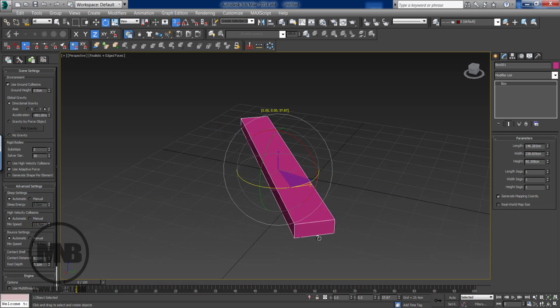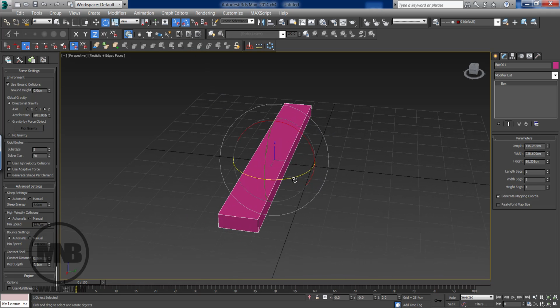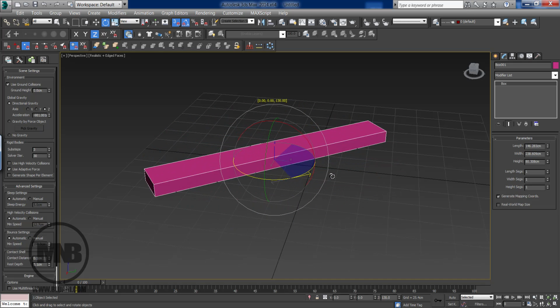If I want to snap, let's say 45 degrees, it's really hard to snap to exactly 45. It's a bit hectic because I have a decimal number. What I have to do, basically, is turn on my angular snap, and now I can just rotate this, and it's going to snap every 5 degrees.